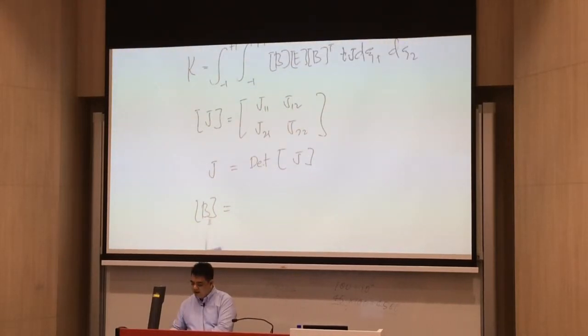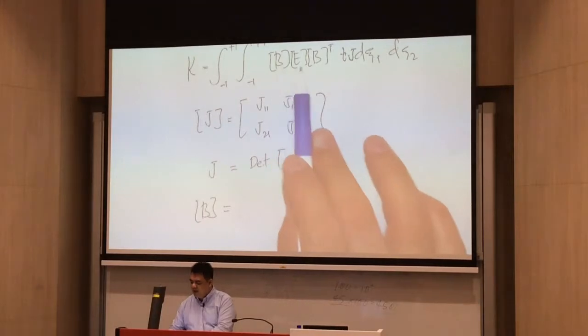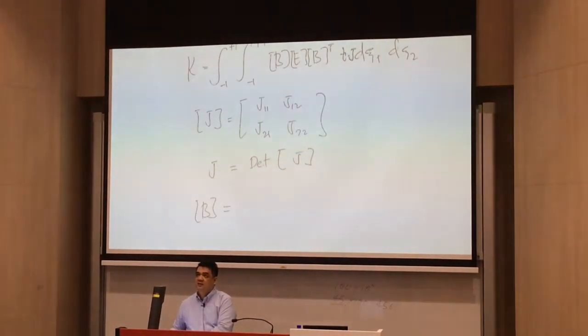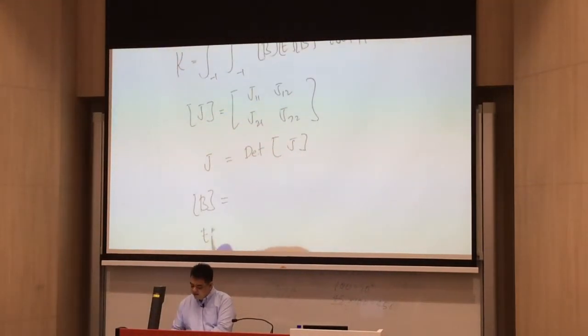So once you have that, you can have now a value for B, E, B transpose. Because E, you can simply use a plane stress or plane strain assumption.